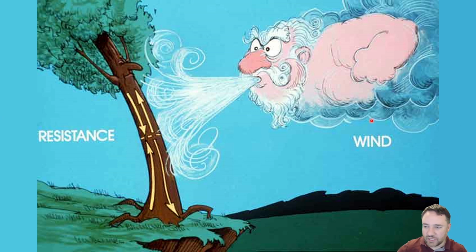So if the wind is pushing towards the left on this tree, the right side of the tree is going to be in tension, and the left side is going to be in compression. Those are just the bending stresses in the tree. And there is some shear, but not a lot compared to these primary forces here. And there's no load on the tree that typically smushes it like this, so it doesn't have to be very strong like that. There's no load on the tree that tries to pull its fibers apart, so it doesn't have to be strong like that. So the tree wood mechanism for resisting that load is very efficient, actually.